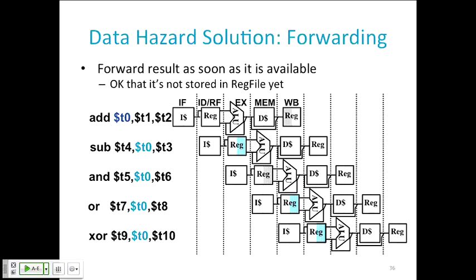right? And similarly, for this instruction, it's even easier. This just needs the value here. I know the value at this point, so I can forward it from here to this input, to this ALU. These guys don't matter. And these are the forwarding paths I'm going to add to the hardware design, right? So the key here is that I know the value, I've already computed it. It exists in the machine at that point in time. I just need to route it by adding some extra circuitry to get from where it's produced to where it's needed, right? So by doing this forwarding trick, you can execute these instructions in one of the pipeline clock cycles, even though they depend on each other.